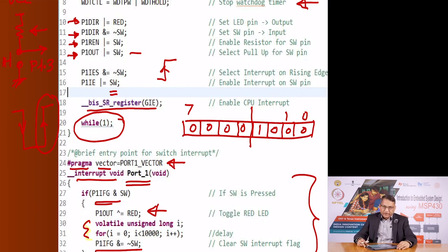And why do we call this example of interrupt subroutine not a good example? It is because we have used a delay subroutine. We do not recommend using delay subroutines in the interrupt program. Now, how do we deal with this? Well, make sure that you do not have to debounce your switch. Now, if the switch is read using polling, this is a good method, but reading a switch or debouncing the switch using delay in the interrupt is a complete no.